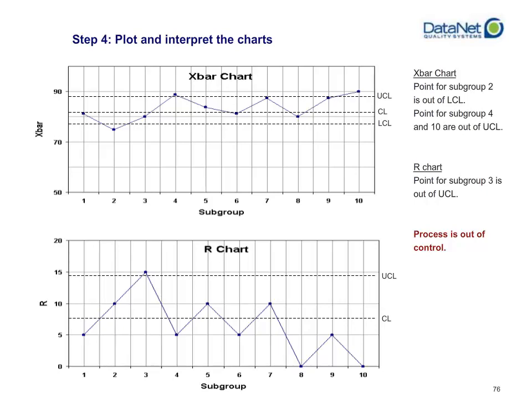But your R chart is also showing some information. With regards to volatility, you're not seeing a whole lot of volatility within the process. However, for subgroup number 3, even though subgroup number 2 was in control with regards to the average, the range in between that data was 15. It was higher than your upper control limit for your range value. So you may want to see why your process was so volatile. Perhaps your process was changing dramatically.